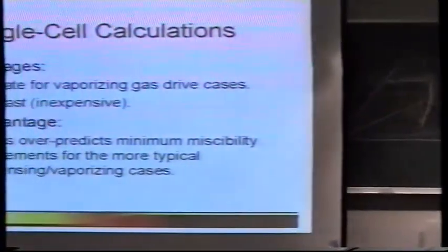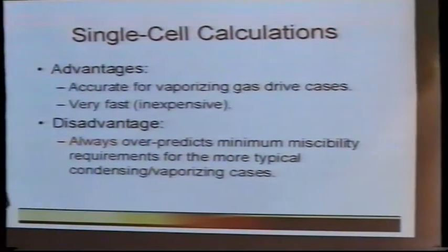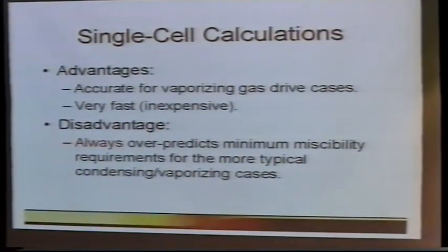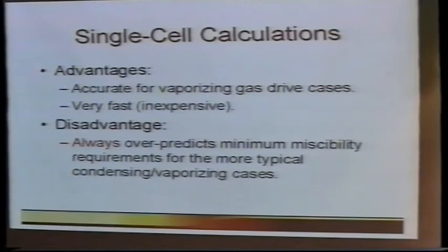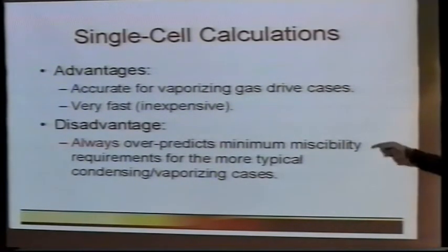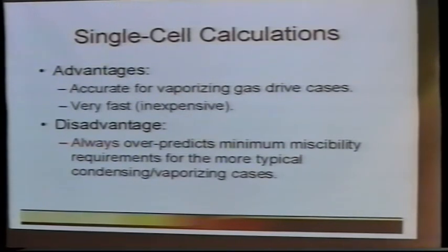And it's perfectly accurate for vaporizing gas drive cases. The problem is that it always overpredicts the minimum miscibility requirements if you have the more typical condensing vaporizing mechanism.